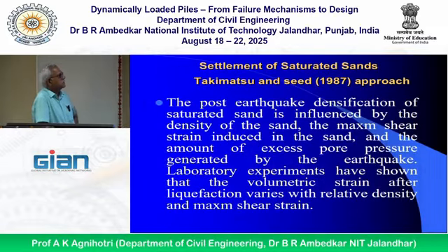Another approach is Takematsu and Seed approach, post-earthquake densification of saturated sand, that is influenced by density of, that was for dry sand. Now for saturated sand, maximum shear strain induced in the sand and the amount of excess pore pressure generated by the earthquake, laboratory experiments have shown that the volumetric strain after liquefaction varies with relative density and maximum shear strain.